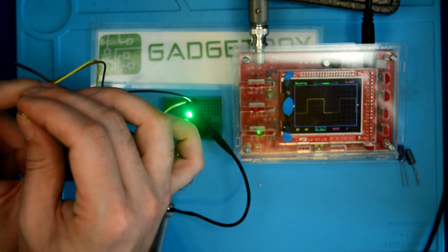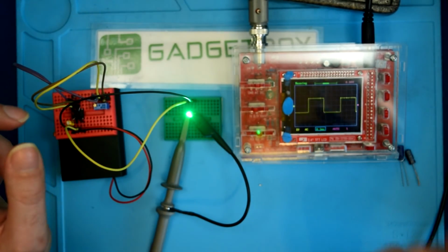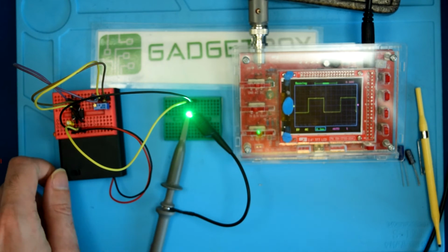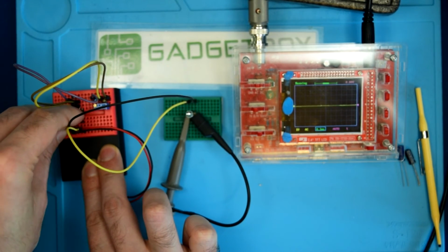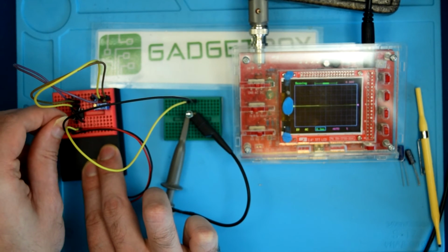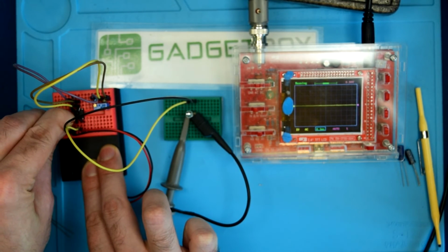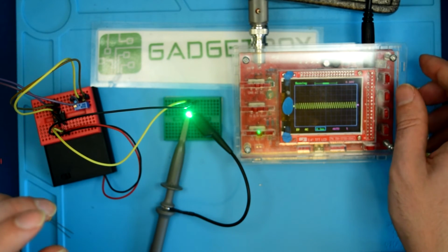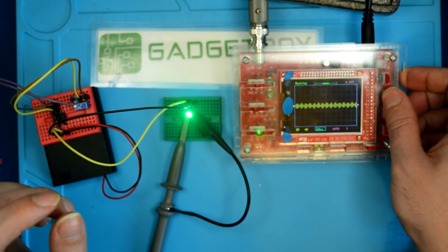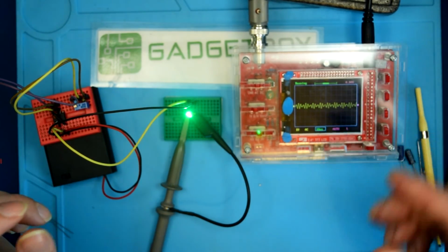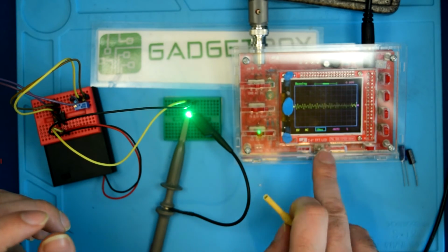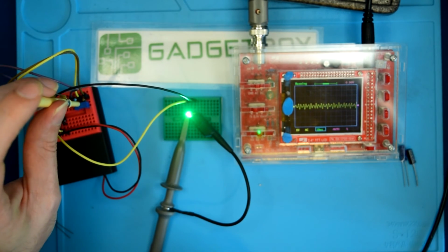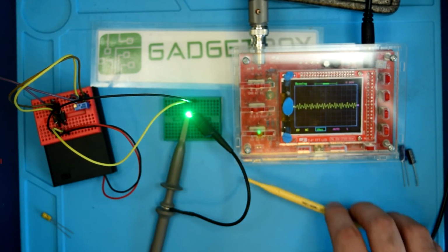And at some point, I'm actually going to be setting up a pulse width modulation circuit to drive these LEDs through my linear driver. But that'll be an upgrade for later on down the road. Now I can make this even faster, but I don't think we'll be able to capture a decent waveform, because when I'm using this to drive my LEDs, I'm going to be running it in the megahertz range. Yeah, I can't even get a solid waveform on that because I think this is only rated up to 200 kHz. And this is running at 1.2 megahertz. So the oscilloscope isn't going to give us a decent waveform.